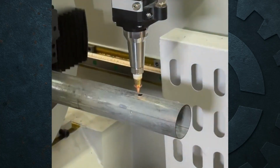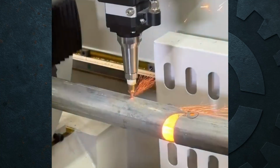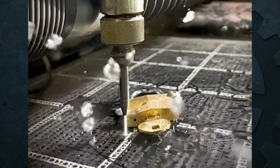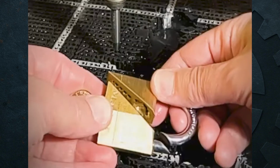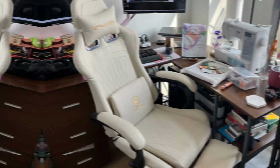For cutting operations, laser cutting uses a focused beam to precisely slice through materials like metal, wood, or acrylic. It's clean, fast, and perfect for sheet metal work. And waterjet cutting, using high-pressure water mixed with abrasive, can cut through almost anything, including stone, titanium, and glass, with zero heat distortion. These processes may not always get the spotlight, but they're essential to modern life, from your car's rims to the chair you're sitting on.